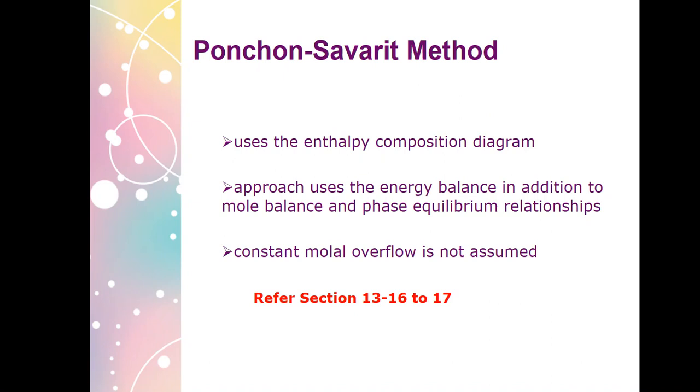But nonetheless, for your information, the Ponchon-Savarit method uses the enthalpy composition diagram, aside from the equilibrium diagram, wherein we can draw together with the 45-degree line and the equilibrium curve our operating lines. And in the case of distillation, we have 3 operating lines for that.